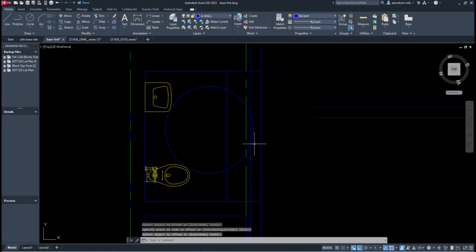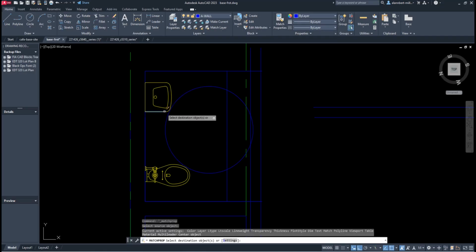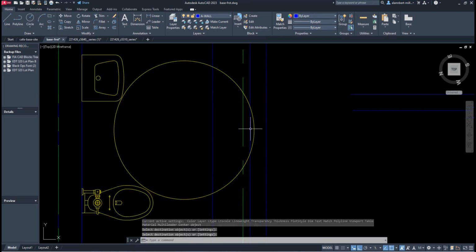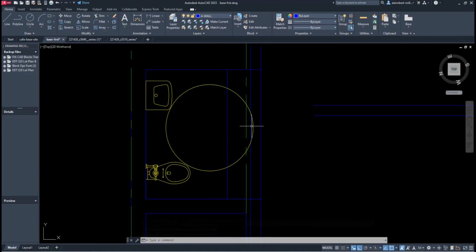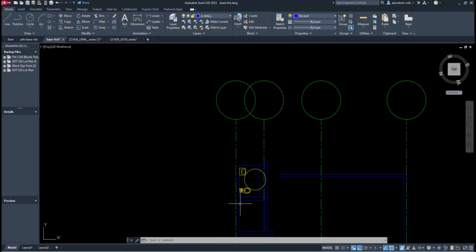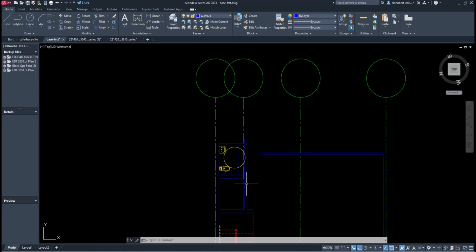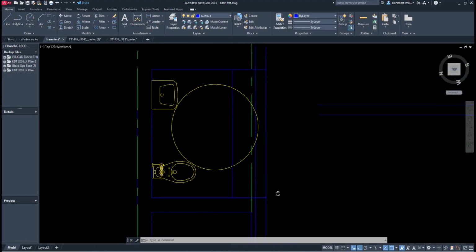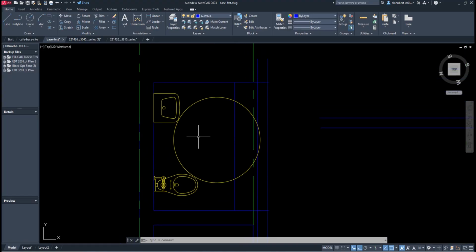And that's 7. It looks like I won't fit because here is my 60-inch clearance. And this is my wall over here. This blue line is my wall. And you can see that they do not fit. So that means that this space over here, the depth of my elevator shaft, will not fit onto my bathroom. Or if I use this wall as the edge of my bathroom, it will not fit. So I have to think of a different way on how to achieve this clearance.